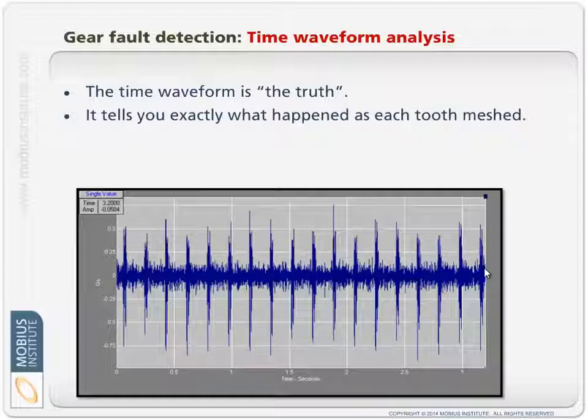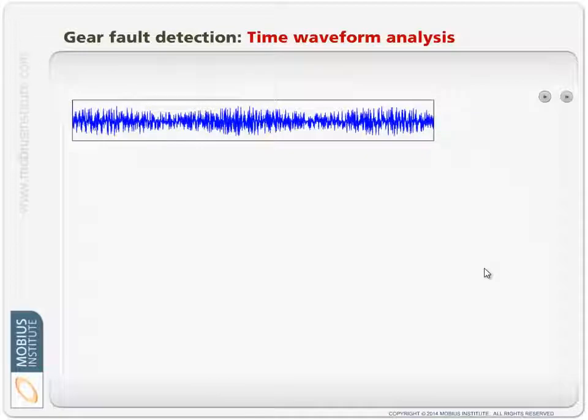But when we get even more complicated time waveforms, or therefore vibration from the machine, the FFT becomes even more limited. What you've got to imagine is we have this vibration just coming from the machine, whatever it looks like, and the analyzer grabs a chunk. The time of this chunk, or this time record, is based on the lines of resolution setting.